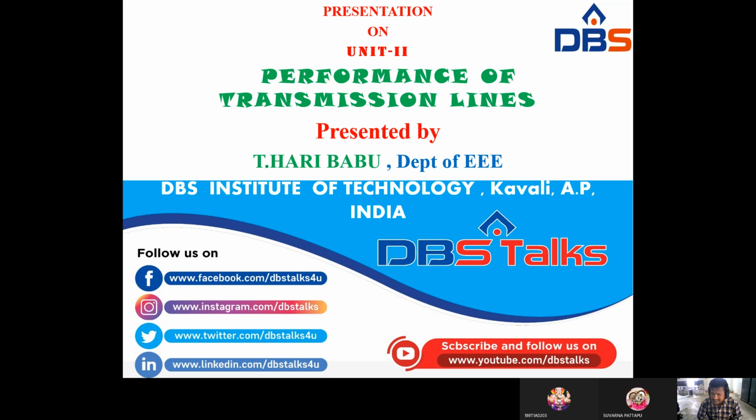A is always unitless, B is impedance, that is in ohms, and C is in mho or siemens. Why is C equal to 0 in this short transmission line? It can be said easily: there is no capacitive effect, there is no shunt admittance branch, so C is equal to 0. Very important for competitive exams for 1 mark. What are the ABCD constants for short transmission line? A equal to D equal to 1, B equal to Z, C equal to 0.